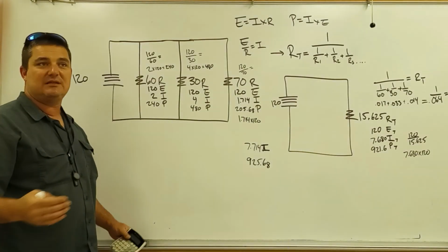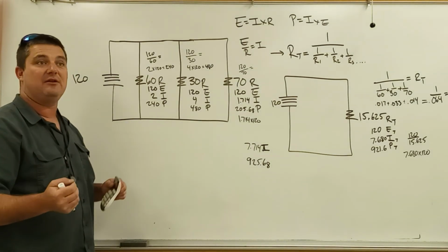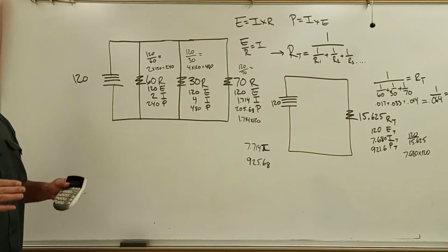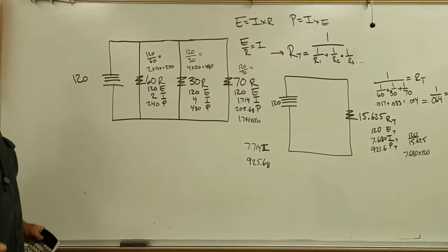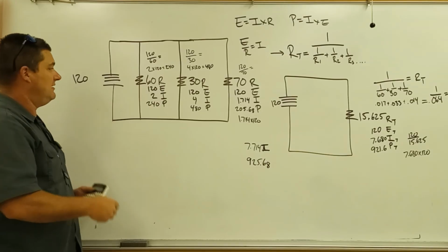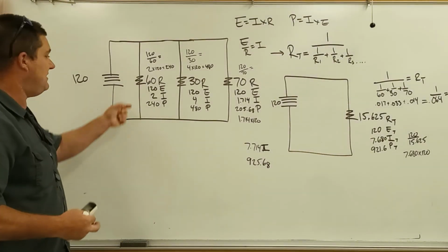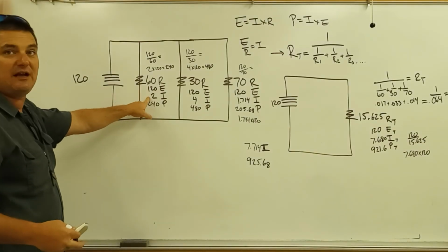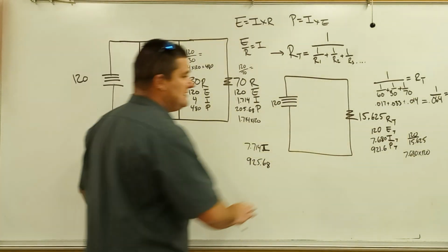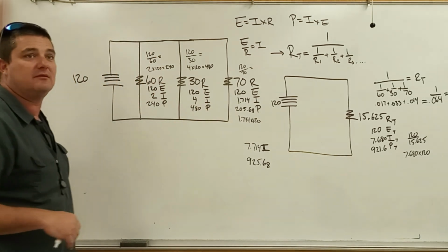And then just like if you're working in the field, you do the math theoretically, then you bust out your meter and take that reading with your electric meter. That way you're verifying with that meter that what you know to be factually true is what's happening. So if this was your conductor on that circuit, you could put your clamp meter on that conductor and you know that it should have 2 amps of current flowing through there. So that's the reason I make sure to get all the way to my totals, and then I just work my way backwards.